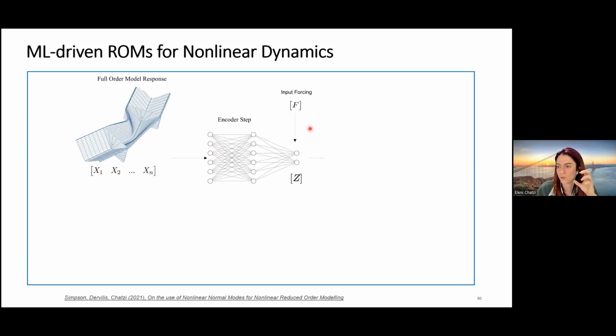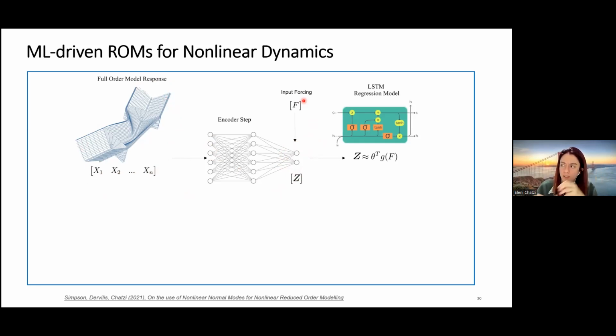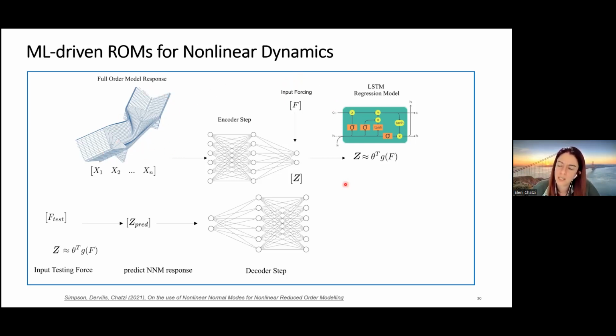And because we describe a dynamics phenomenon, we use this lower dimensional space, and we try to develop essentially a time series model, an autoregressive type of model, which is now delivered through an LSTM, a bit dissimilar to what I showed before, but very similar in logic, where we now have the dependence of the force we're inputting into the system with this lower dimensional representation. This is propagated in time, and we can actually simulate the whole dynamic response of a quite complex system, although this takes place in these reduced non-physical variables.